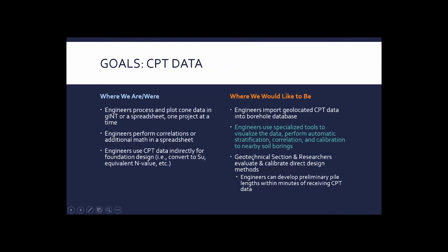With our cone data, we would generally receive individual data files from the drill crew, and then the engineer would process the data and plot the sounding logs. Usually, you take that CPT data and indirectly correlate properties for foundation design. We do some direct design methods now, but where we started was indirectly using CPT data.